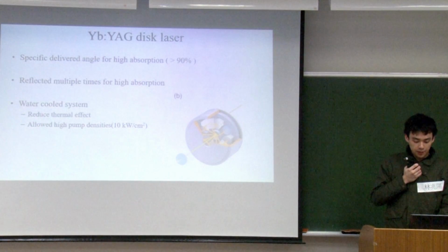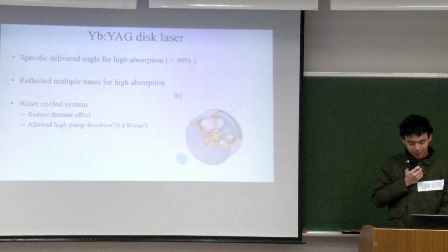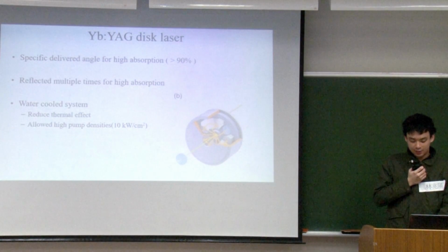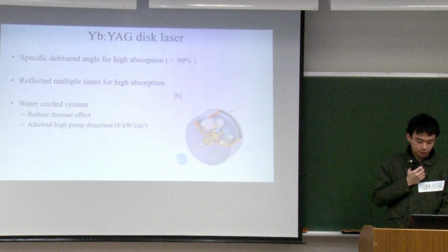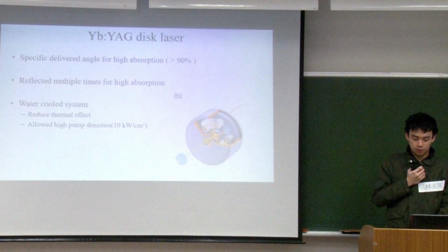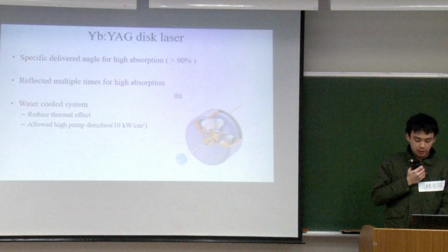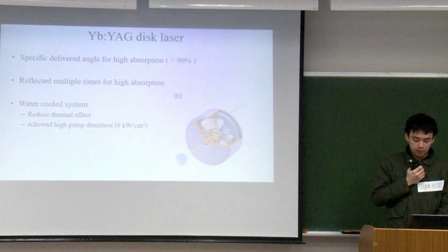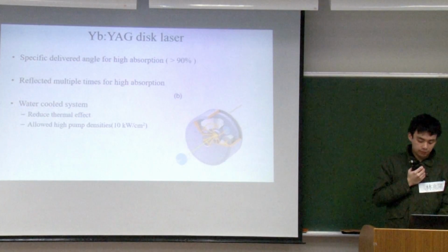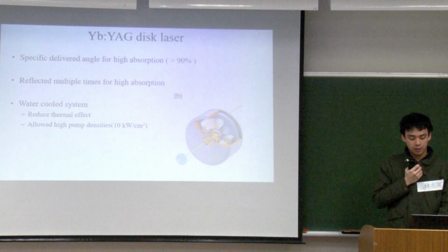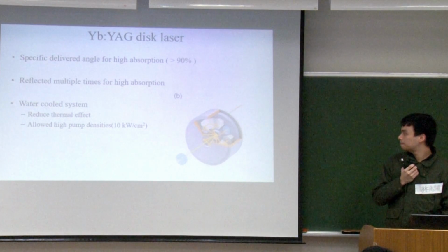The pumping light will be delivered in at a specific angle and pass through a well-designed optical path for higher absorption. And with the aid of the water-cooled system, the thermal effect on the optical properties is reduced and allows a higher pumping density.